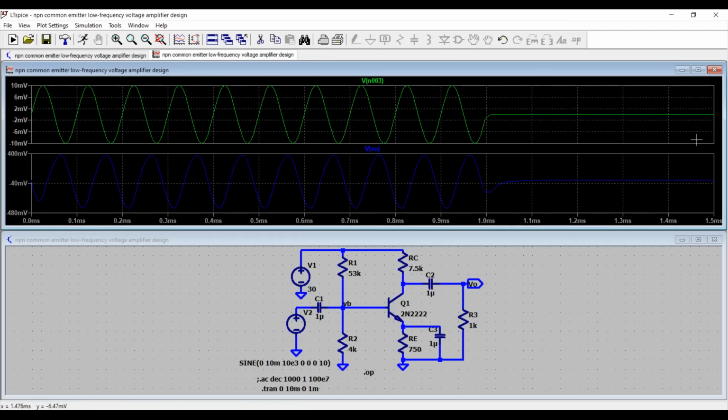Remember, in this one, we had the gain, which was set by the ratio of RC divided by RE, and this is 50, and this more than 50. This is in theory, and AV is approximately 45 in simulations, and that's correct, and it is really having that one, right?